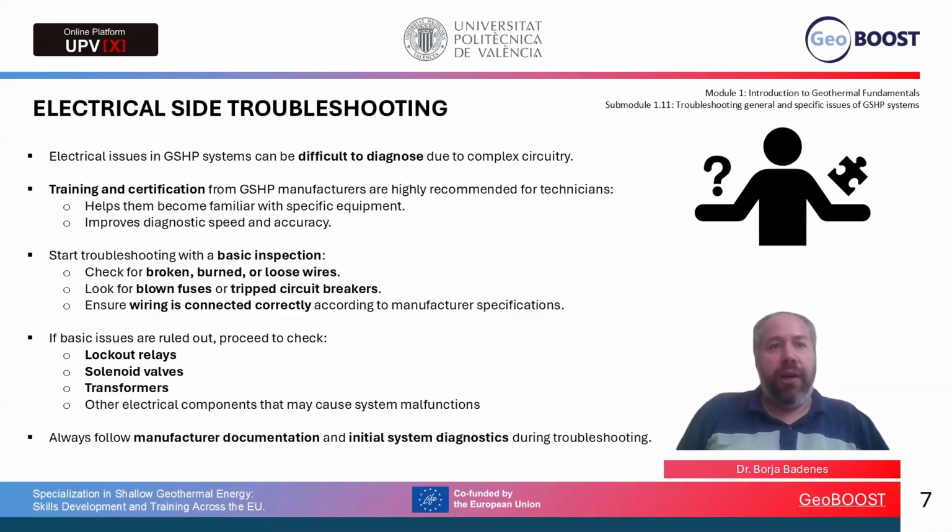If all basic checks pass, take a look at relays, solenoid valves, transformer, or other parts. But please follow the manufacturer documentation at every step.